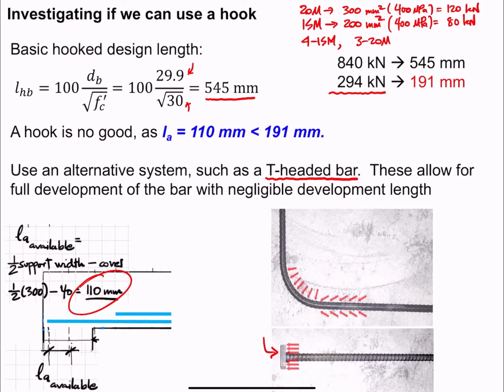And remember, bearing is going to be very effective, because it's going to transfer just those forces into the concrete in compression. All this concrete here is going to be in compression when you pull from that bar. And with a relatively small area, you will be able to take all the force in that bar.